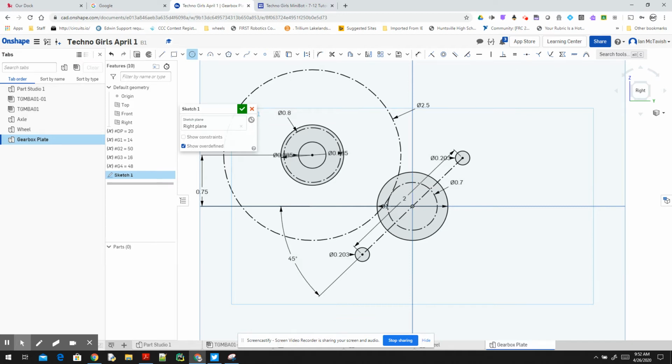And you can see this sketch is starting to get fairly busy. That's why I'm kind of adding these as I go. So G4 is my last gear. Again, it's a circle and it's a construction. So I'm going to click up in some space here, and I'm going to make sure that it gets orange with G3, which is the smaller of those 2 circles right there. And I'm going to click and just hit escape, and the dimension tool to now set the diameter. So this is G4 divided by dp, and enter. So I now have that.